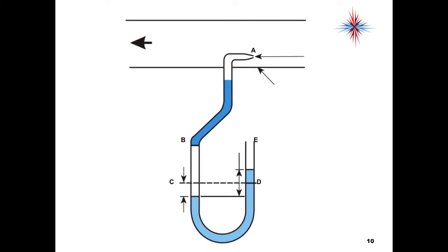Now we connect it into ductwork, and you'll see that the left-hand side, where C is, dropped, and where D is, it increased. So we now have a pressure difference between the room air and the area within the ductwork we're measuring, because that's really what we're measuring. We're measuring a difference in pressure.